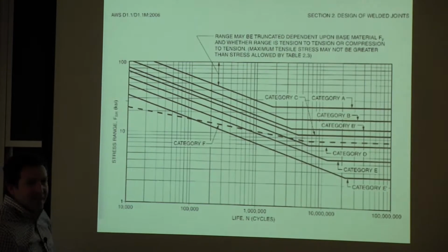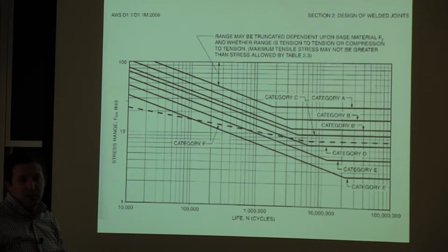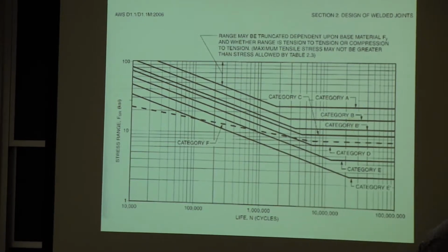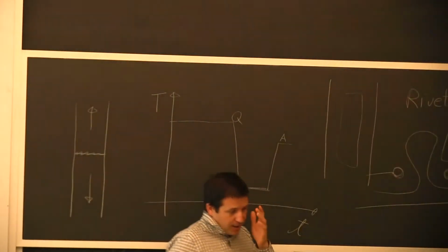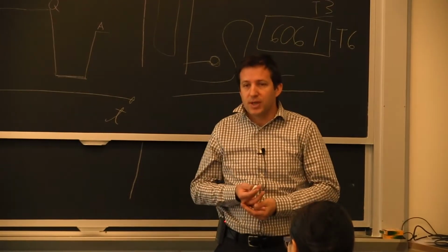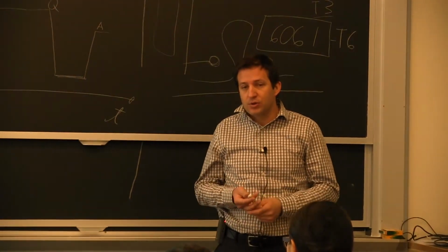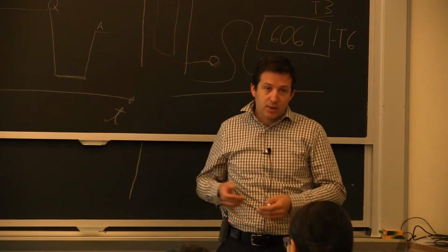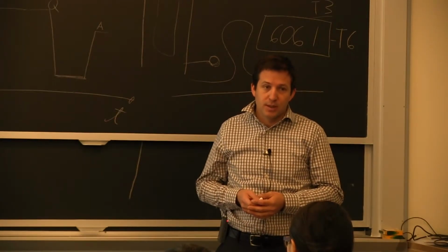You're looking at a stress here that's less than 3 KSI. So it's a factor of more than 5 on what you're permitted. And the main reason is all the residual stresses, the change in microstructure, the heat affected zone, will form cracks in condition where you wouldn't have cracks otherwise.